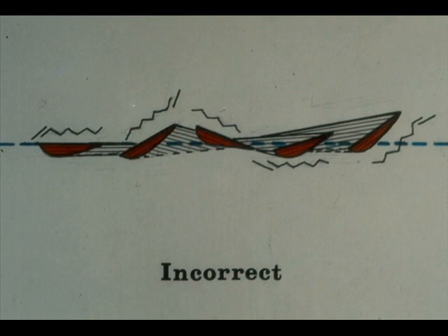Here's something else to remember. All of the blades on a fan should be set at the same pitch. If they are not, an aerodynamic imbalance will result, and the fan will vibrate until it destroys itself.